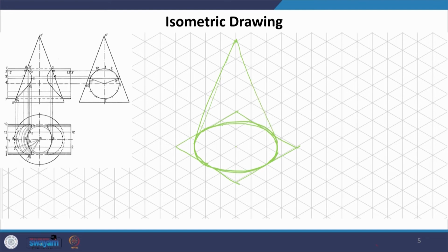Now, what is happening is that this cone is being intersected by a circular cylinder, which is passing like this. Now, look at it in elevation, and we have to draw exactly the reference plane at the right place. So, if I look at it from the top, this is where my reference plane is, right. So, this is exactly what I am going to draw here. So, say this, it projects like this and to the back also. Now, if I look at it in elevation, this is where my reference plane is going to come.